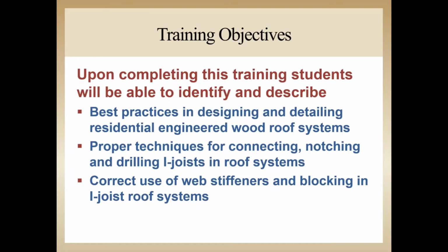Now, I-joists are often used in commercial roof applications, but today's training module will focus on residential pitched roof systems. So our training objectives for today are to help you be able to identify and describe the best practices in designing and detailing residential engineered roof systems, the proper techniques for connecting, notching, and drilling the I-joists in those systems, and of course the correct use of web stiffeners and blocking in the same systems.